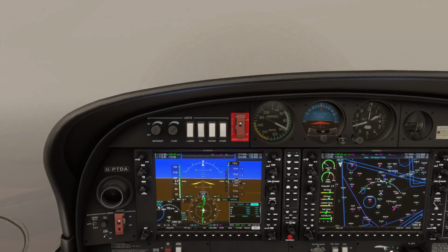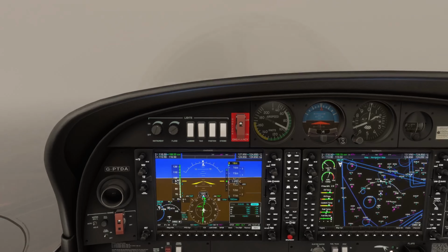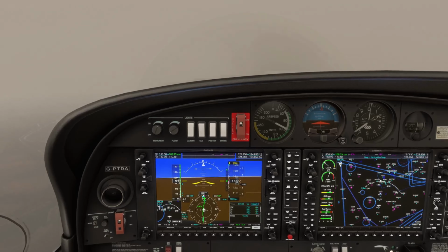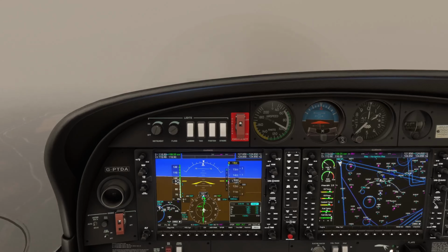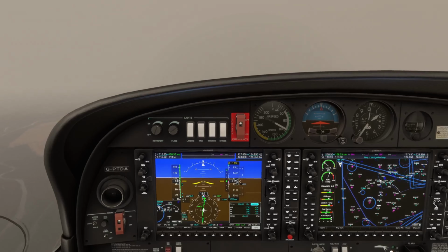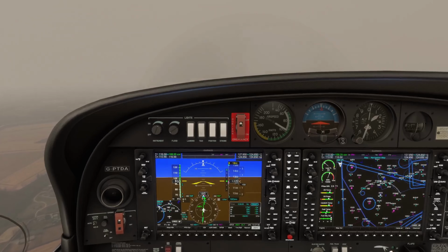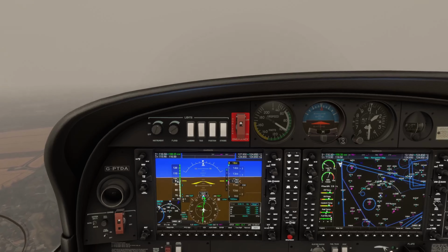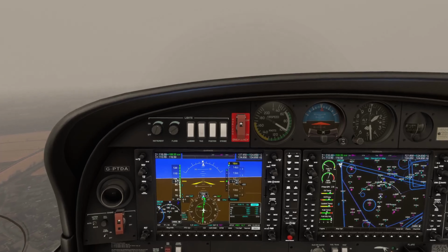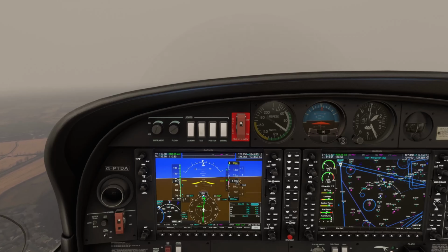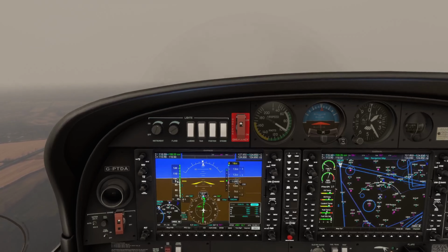We don't have to worry about checking the altitude, as we have the vertical guidance. If this was just a localiser approach, we would have to check it, but in this situation we don't. So it was 5 knots too fast, but that is fine. We do have that headwind as well, so we're just adjusting to maintain. So we're pretty much on speed, we're on glide slope, trying to maintain that altitude.